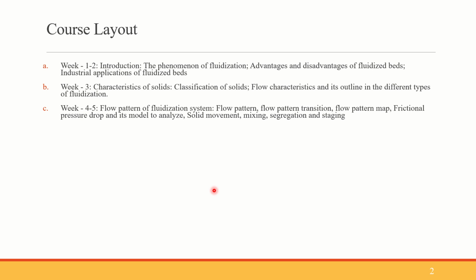So we can see various regimes like bubbling fluidized beds, slugging fluidized beds, turbulent beds, and fast fluidization regimes. After that, we can also see pneumatic transport where the particles escape from the bed, and there comes a need for recirculation of the solids so that there is no material loss and also the optimum level of solids inside the bed is maintained.